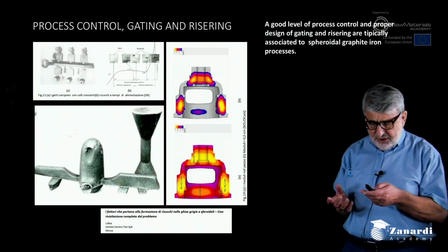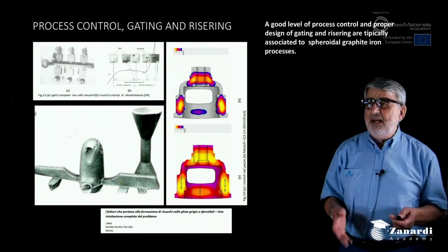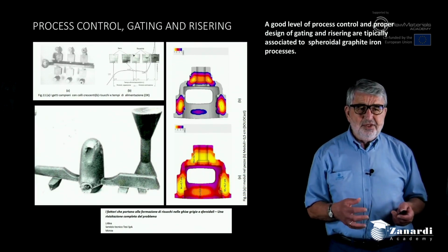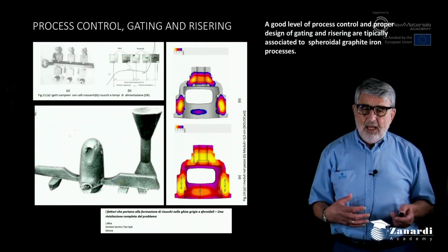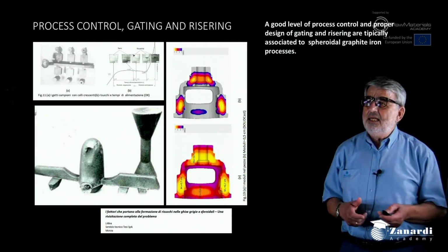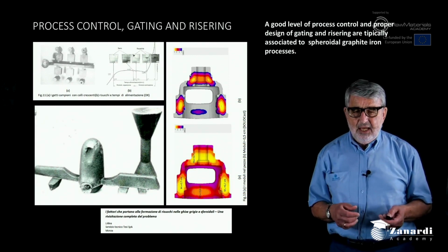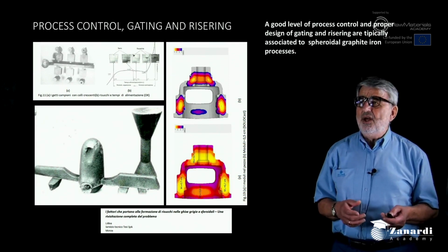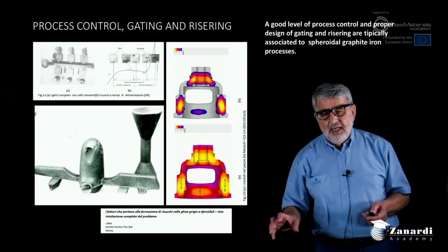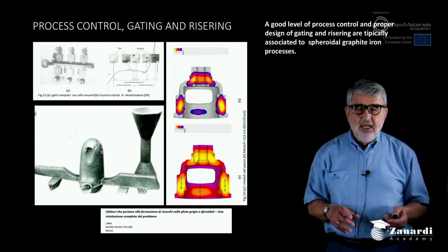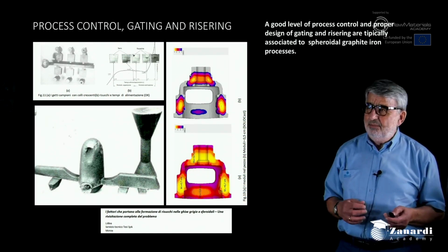And this is done typically using numerical simulation of filling the mold by using the Navier-Stokes equations, and also simulating the heat transfer into the mold using the Fourier equation, but coupled with a material modeling that is able to simulate the latent heat release following the mechanism I described previously.